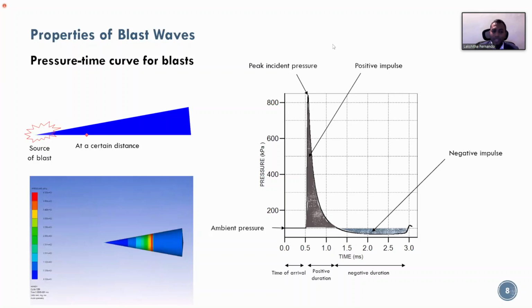If I can use a different analogy, it's like when you go to pump air to your tires, right? If you empty the tire completely and take the reading, it's going to be 0 psi or whatever the units used. But that doesn't mean that there's no pressure. There is atmospheric pressure. So when you pump, say 35 psi or some quantity, what you mean is it's 35 psi over and above the atmospheric pressure.